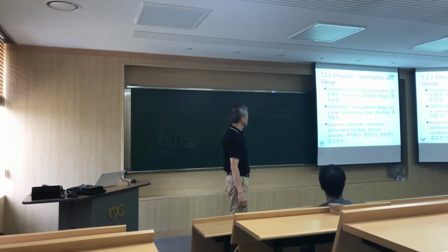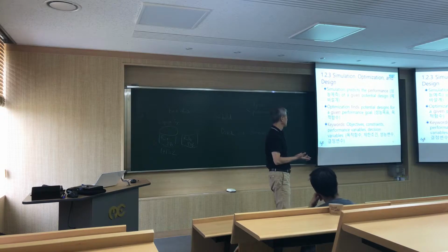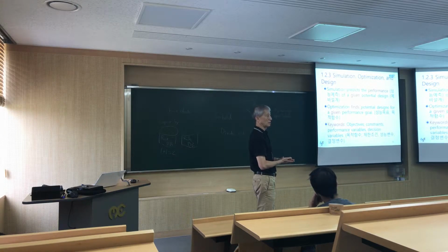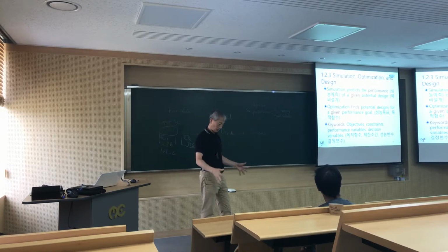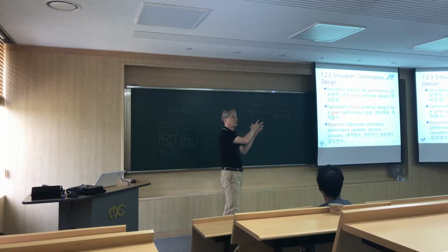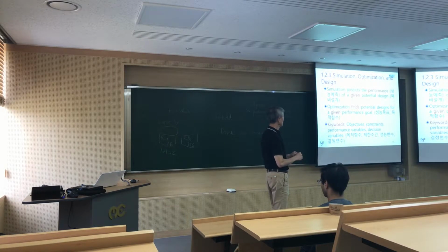Another strategy is optimization. Simulation is trying to emulate the physical world, right? Simulation, by using computers. So why? They want to predict the performance of a given design. Right? The concept car for the next year exists only as a concept, and it can also be made into a sketch. And then using the sketch, you can convert it into a computer model and then do analysis: finite element analysis, computational fluid dynamics, cost analysis, durability, any other things. Right? So that kind of thing is simulation. Computer simulation of structural performance, hydrodynamic performance and economic performance.